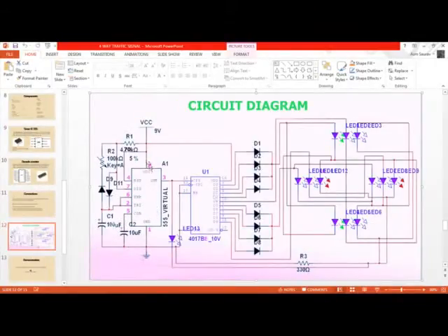By the way, we have connected VCC to pin 8 and pin 1 to the ground. That's simple. And we're taking output from pin number 3. Here's some tricks. I mean, not tricks, like there's an LED here. I'll talk about it later.